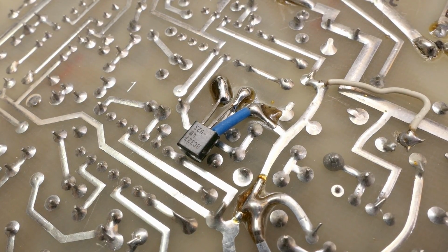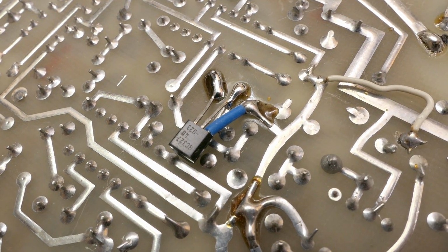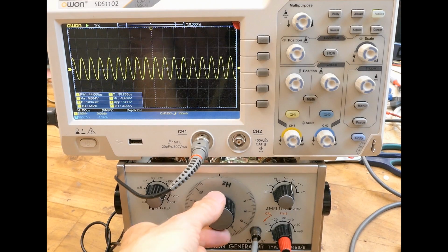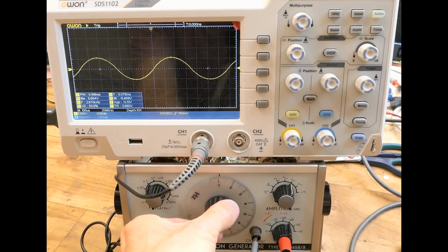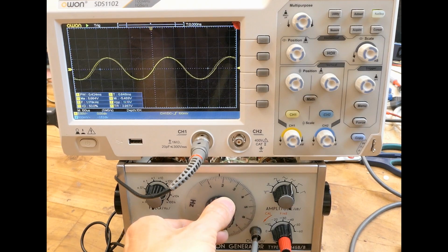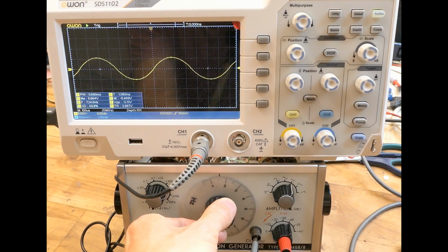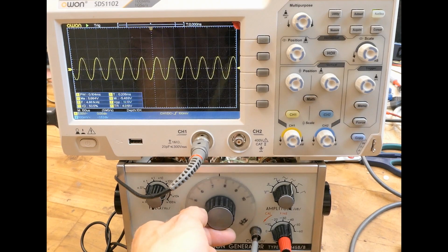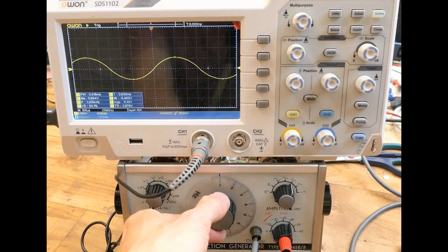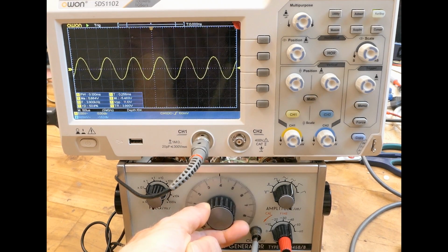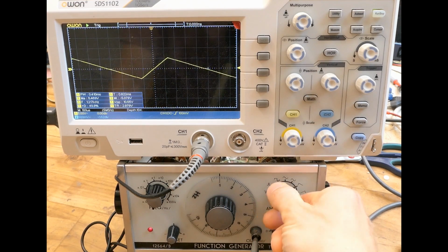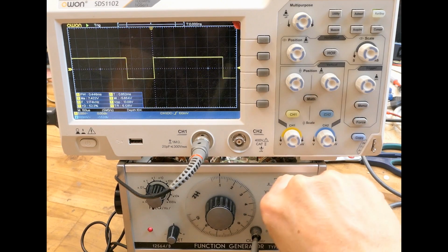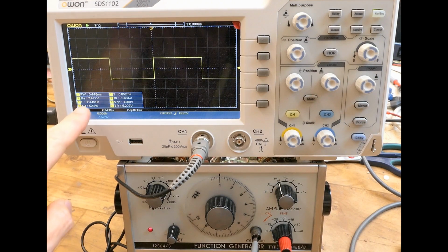I just horribly botched it on the other side to see what happens. And testing time. And it seems to be a nice sine wave everywhere. No distortion. In the lower half of this fine frequency potentiometer where it was previously distorted, now it's not. It makes nice waveforms. The square wave duty cycle should be 50% and it's 52.3.